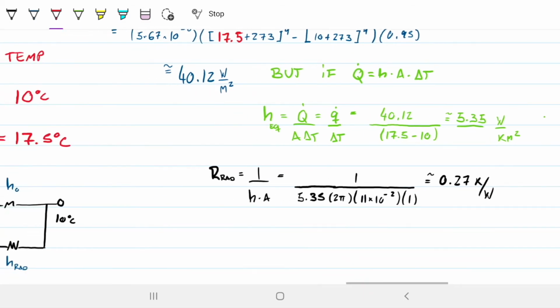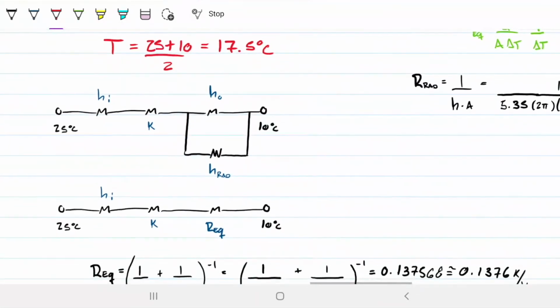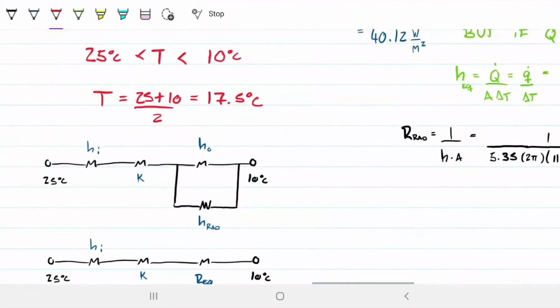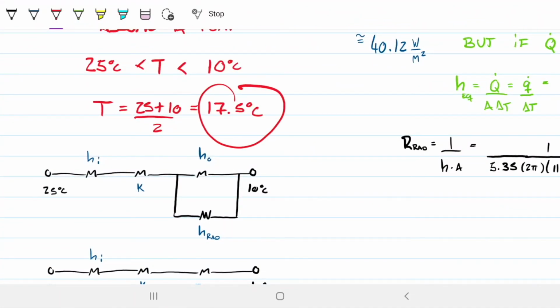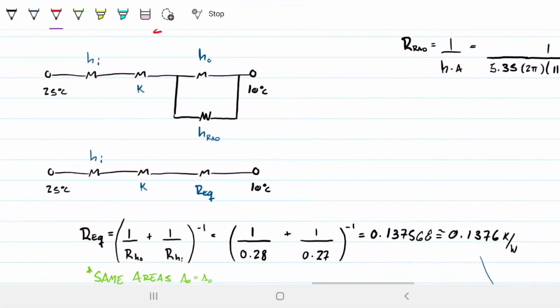So the first circuit that I draw already has the parallel system with the radiation and the convection competing. Well, this converges exactly to the same value as before, but it converges faster because our first guess is already closer to the final answer. In an exam setting, this is just your lucky guess. You can do whatever is reasonable. So in this case, the process is the same. You just start from different points.